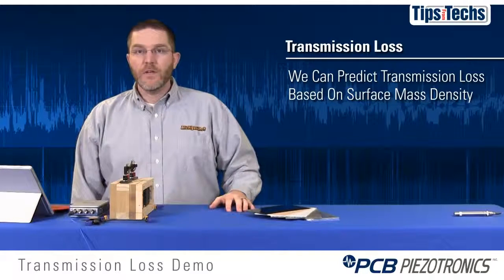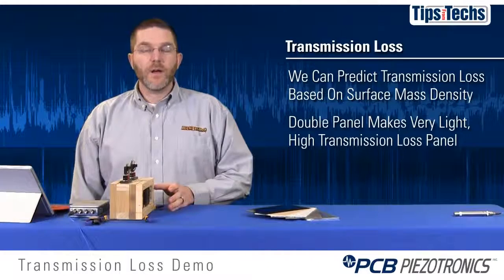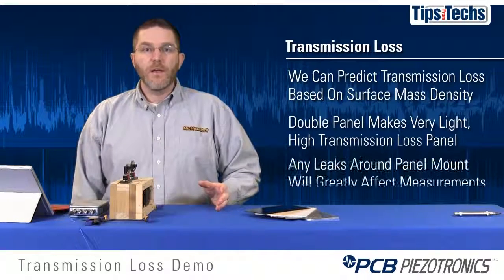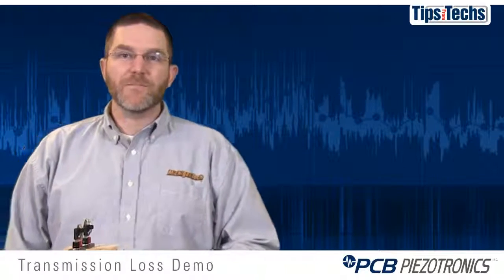But that's not the only thing we need to consider when looking at a transmission loss problem. Remember, the double panel example showed that we can make a very light, very high transmission loss panel using double panel construction. Additionally, any leak area around your panel mount will greatly affect your measured transmission loss. I hope this demonstration was informative, and I hope to see you next time.